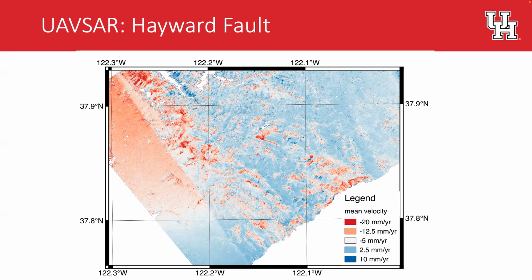Because it's moving so slowly, when we use synthetic aperture radar, that motion can be captured by repeat passes, differential InSAR, and you can actually get a profile of that creep. In this case, you can probably get a fairly decent measurement of the near field deformation.